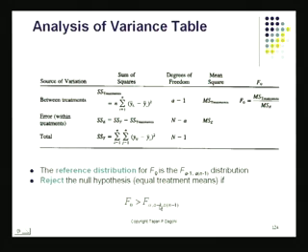If this quantity is bigger than this quantity, that means my ratio, mean sum of squares due to treatment and MSE, is greater than the critical value. And if it is greater than the critical value, I'll be rejecting the hypothesis that mu1 equals mu2 equals mu3 equals mu4 equals mu a. This hypothesis I'll be rejecting. In fact, what I'll be saying is that changing RF power did in fact impact the response, which is etching there.